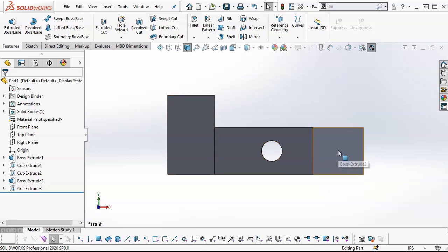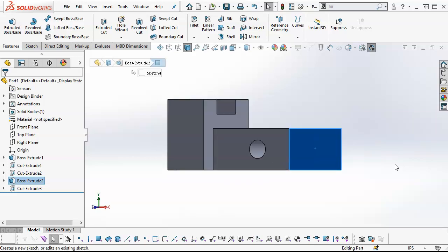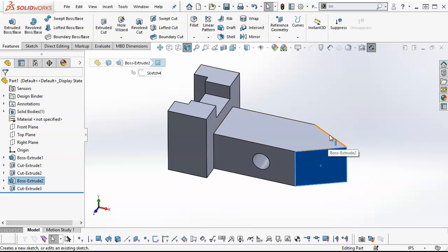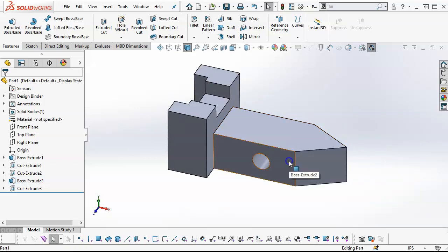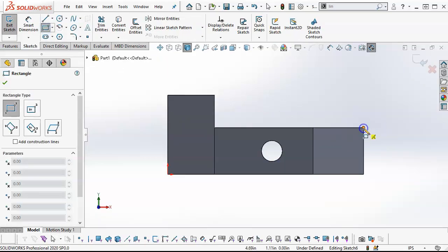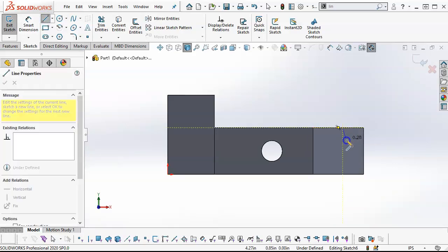So go back to the front, and one of the things we'll need to watch out for is the direction of the cut. So if I open a sketch on this face, it's going to be just like I go normal to. So Control 8, and notice it rotates around. We would generate the rectangle, and the rectangle would kind of go off at an angle. We want it to go straight through the part. So in that case, I'll pick the same face, and we'll generate a little rectangle, or that would give us a closed profile.